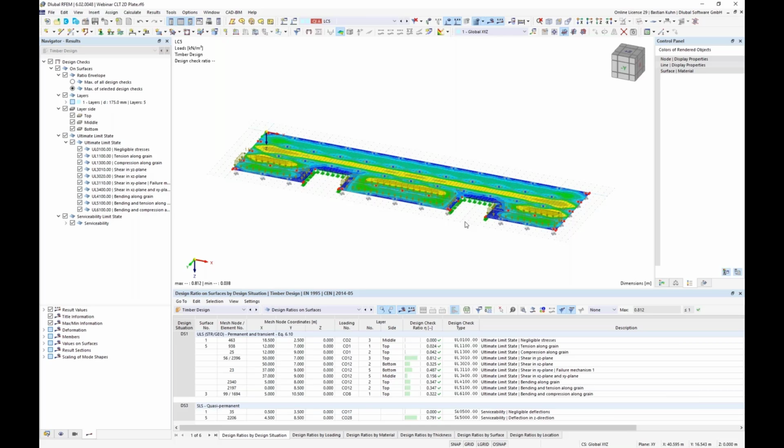You can compare it with a continuous beam. If you have 2 fields, you also have to introduce the live load on the left side and on the right side, because for the middle support, the highest force will be with live load on the left side plus live load on the right side, but the highest field moment is with the load on the left side, if it is the longer span, for example. Okay, so I hope that's clear.